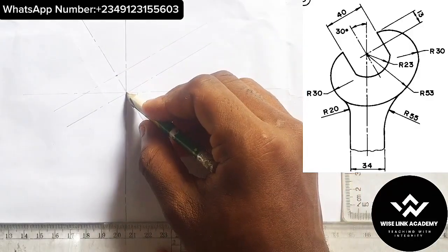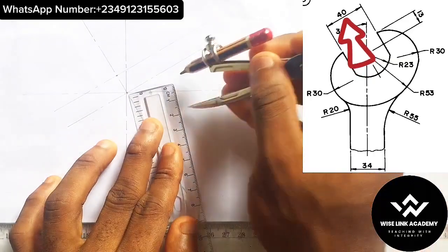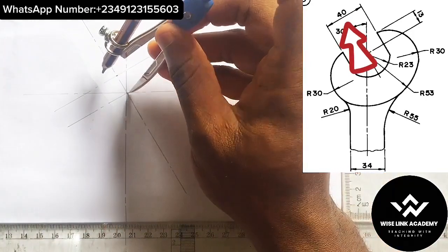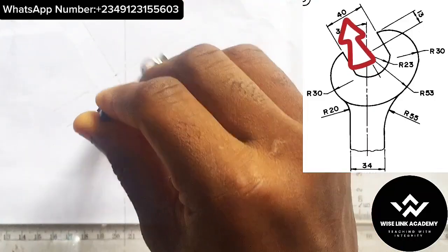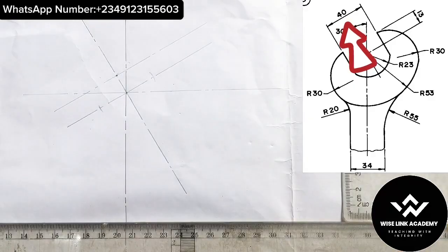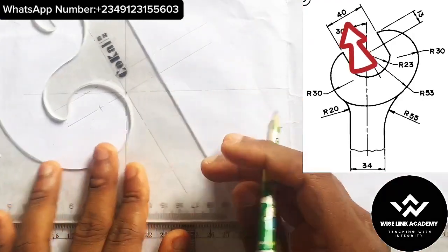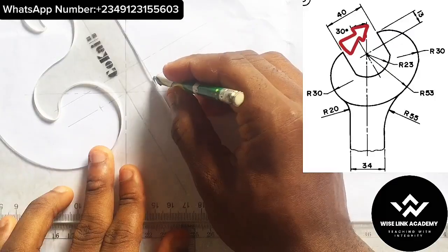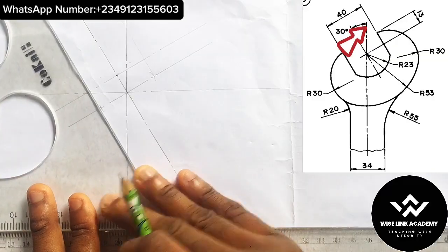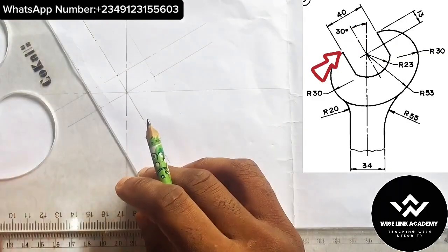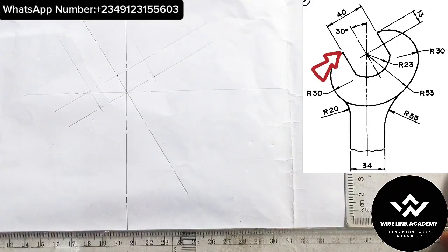So it means that I'll now indicate the 40 distance. So as you can see, I'm indicating the 40. So measure 20. So come to the center point here. Mark 20 to the left, 20 to the right, as in this case, right? So having done that, the next task is that I'll take my T-square in this sense. That point 40, take it upward. Come down here to that same point, take it upward. So I have this. All right, from there now, what's next?